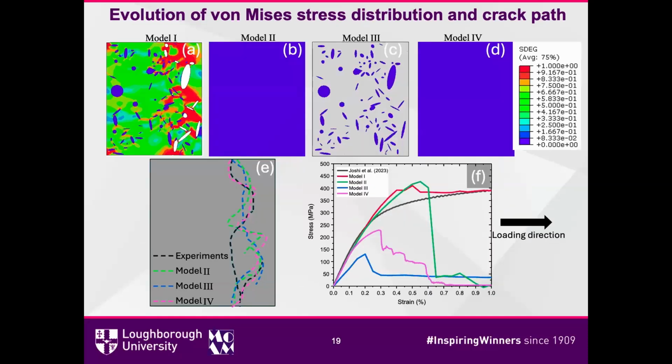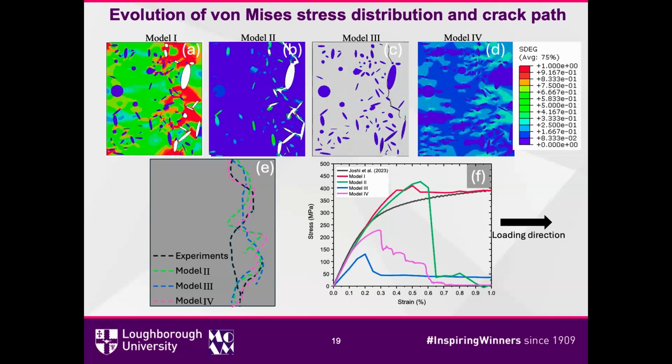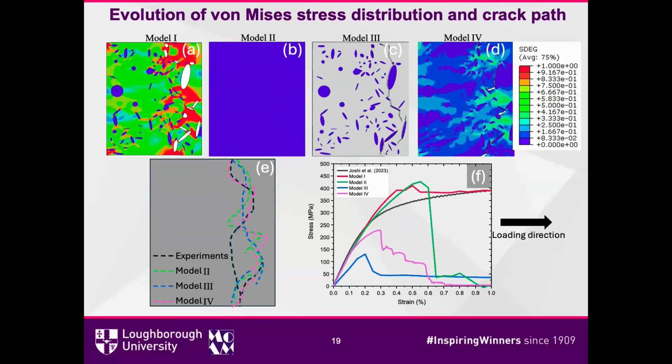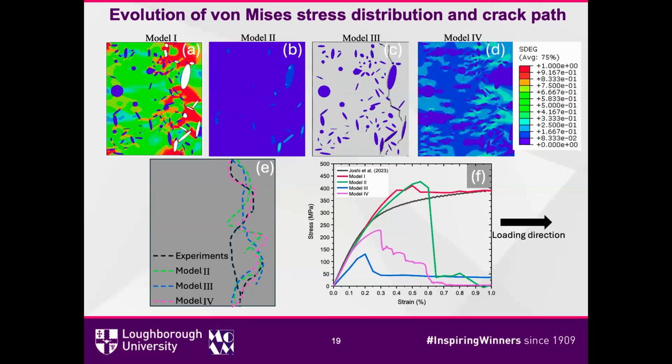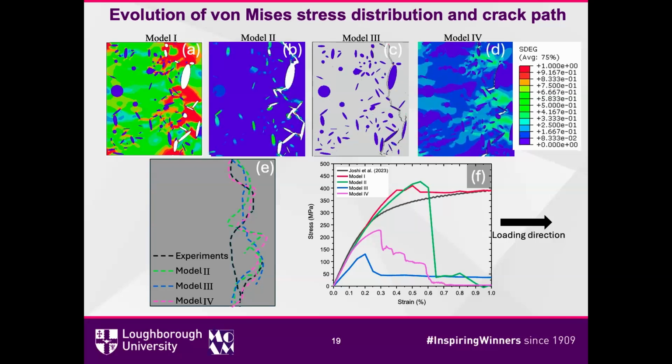So in the following, we use simplified models. The first one has no ductile damage in the graphite, and elastic and plastic behaviors for the matrix. For the second one, we use Johnson-Cook for the matrix, and also ductile damage in the graphite. For the third one, we use cohesive in the graphite and the matrix, and also for the interface.